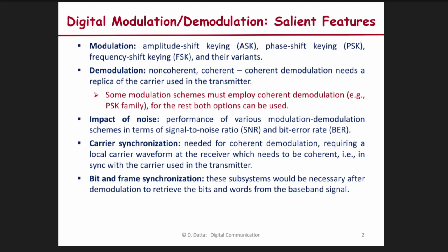Can you see that frequency translation? Yes, sir. You can see that, right? Now if I take another person's speech and modulate with the frequency fc2, then the same spectrum shifts to fc2 and minus fc2. But they are not overlapping in the frequency domain. They are orthogonal in the frequency domain, not overlapping. Similarly, I can take the nth baseband BBn and modulate by fcn. Then it is again offset and translated to fcn and minus fcn.